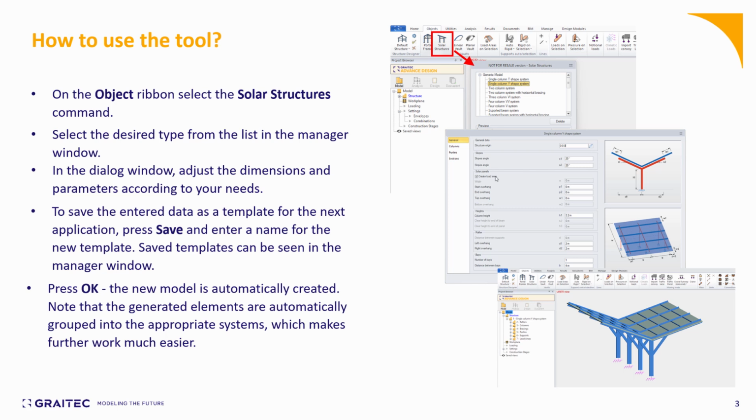After that, we will have the second window, as you see here, to put in the parameters to create the supporting structure. We start with the general dimensions, and we go more into detail to define the columns and purlins and sections, etc., to generate the structure. The dialog box is totally interactive.